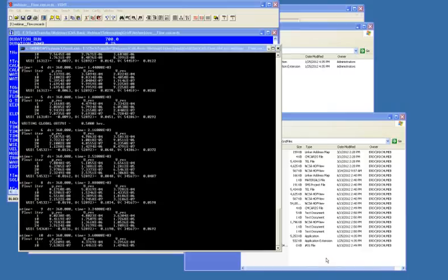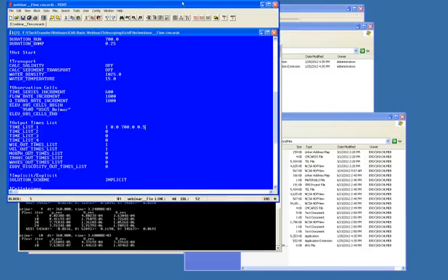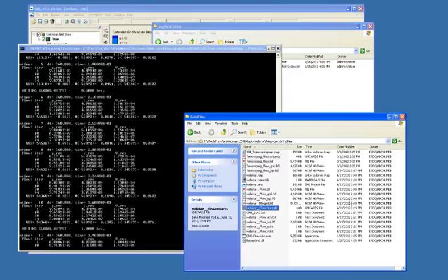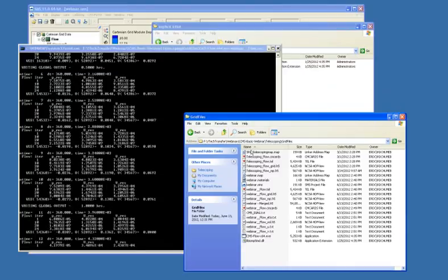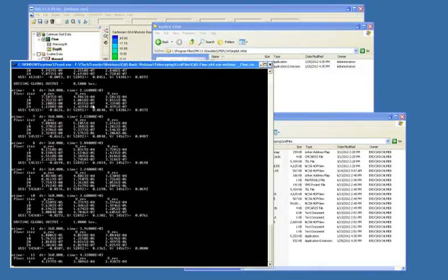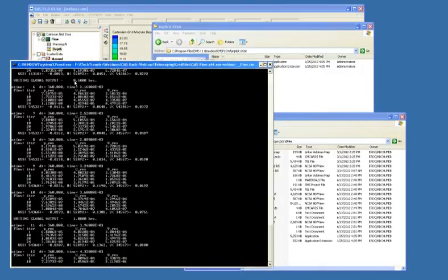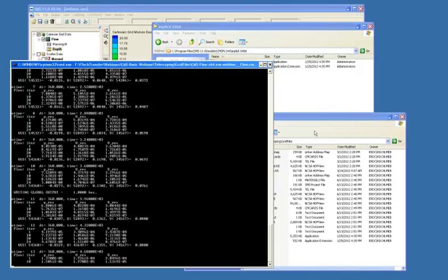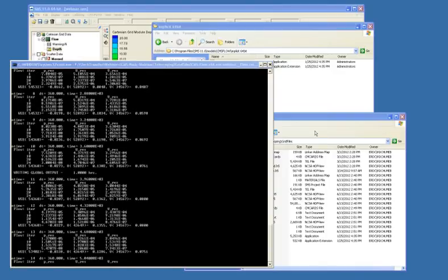Yeah, when we modified the control file, this parameter file, you'll see a difference in the time on that so that you know that there's been a change. All the other files were written at 240. This one's written at 249. But the only other way to tell that it's been changed is now I changed from writing out every 0.1 hours to every 0.5 hours. So you see there's only global output every half hour now. So that kind of tells you that you have made the change and it's actually working.